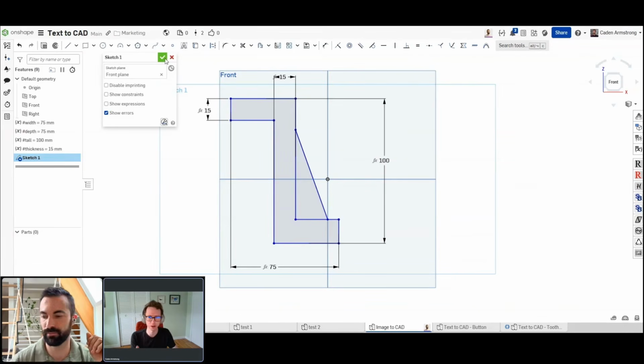Things like not enough base plate or adhesion, knowing I'll have to put a brim and where it needs to be supported and what maybe doesn't need to be supported. It definitely takes me a couple tries. I will design something, go into my slicer, it complains to me, and then I have to go back and rethink the design. And that's experience I just don't have.